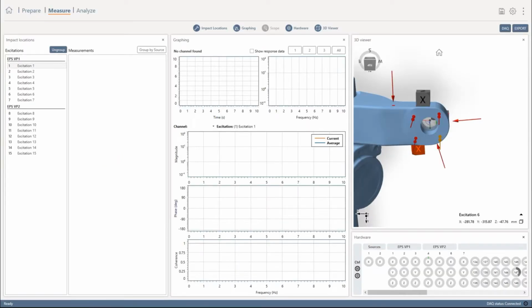Anytime you connect to the DAC or reconnect your cables, you should click here to auto-zero the channels. Right-clicking in the hardware card, we can also customize this view.